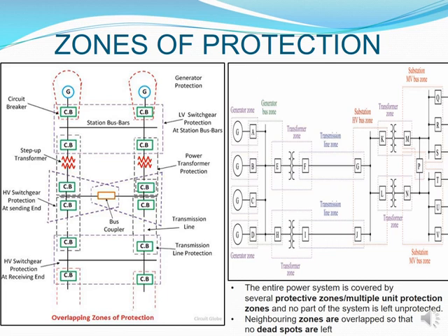So if anything had to happen within that bus coupler, this portion could take it out, or if something were to happen on the bus bar before you get to your bus coupler. Then on your other side, the right hand side, you've got two circuit breakers that are also ringing into this bus coupler, so you have a similar scenario there. If anything had to happen on that portion of your bus bar, then that portion can be taken out. And the nice thing again is that you can always have one side of your bus bar connected into this scenario.